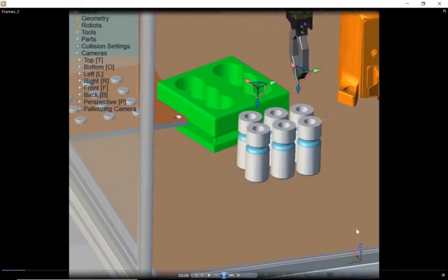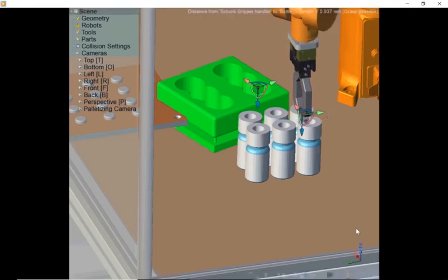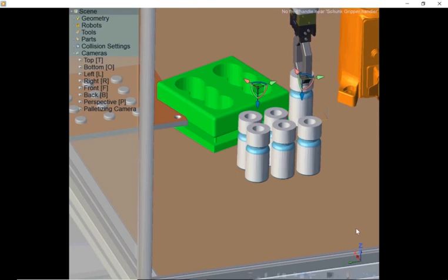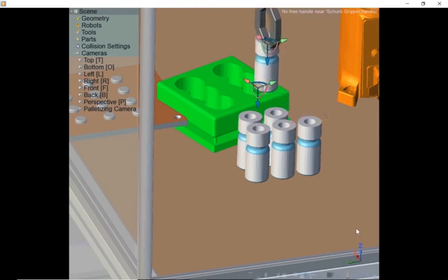So as you can see, we've moved the pallet. We've not only moved it in X, we've rotated it a little bit, which adds a really big problem for us if we were going to do it the traditional way of just knowing the offsets, because the offset would not just be X 45mm or whatever in X. It's also got a Y. So this rotation is quite a problem for us if we didn't use frames.